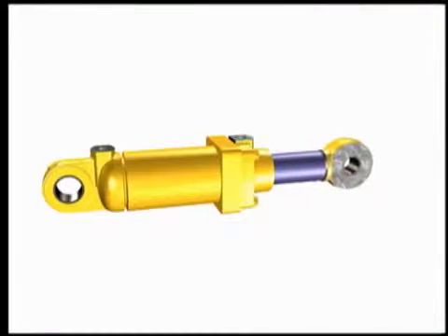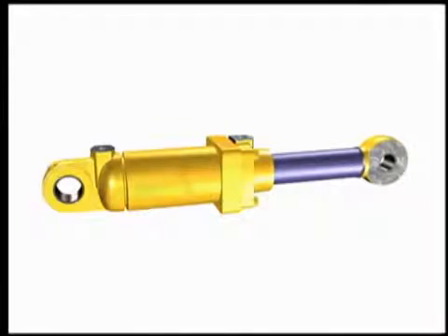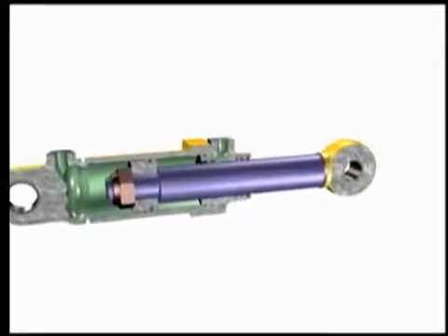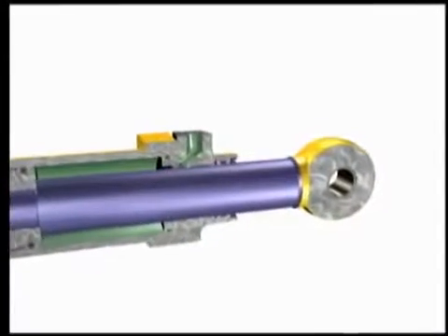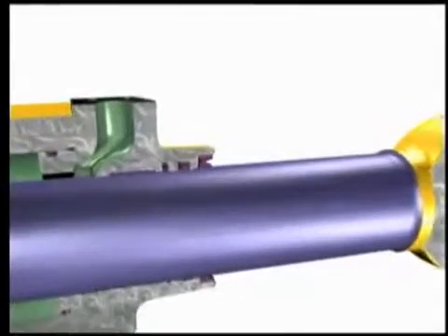Contamination already in the system moves on to hydraulic cylinders, where additional dirt can enter the system because of nicks in the cylinder rod. A wiper seal in good condition will prevent much of the dirt from entering, but contaminants down in the nicks can move past the wiper seal into the cylinder.